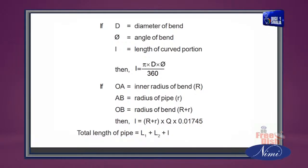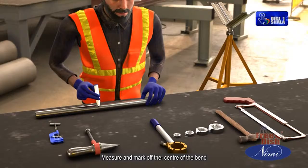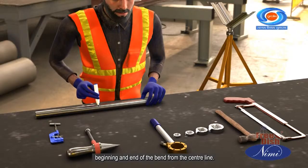Total length of pipe is equal to L1 plus L2 plus L. Measure and mark off the center of the bend, beginning and end of the bend from the center line.